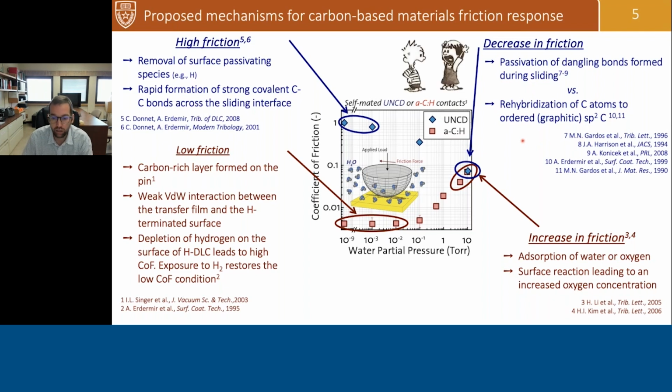I will not go into that topic today, but for sure, from an engineering application, you can see that still we have coatings that have a complete relative humidity dependence of the friction response. From really an engineering standpoint, it's not super important sometimes to have an incredibly low coefficient of friction, but it's very critical to have a friction response that is consistent across different environmental conditions.